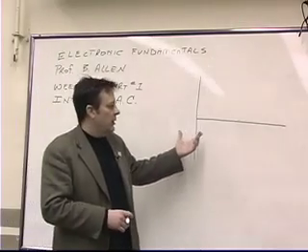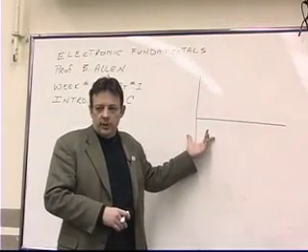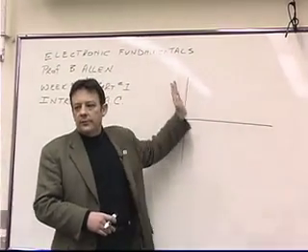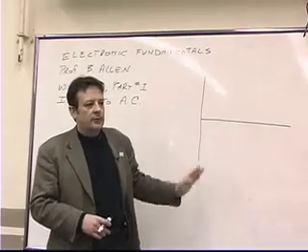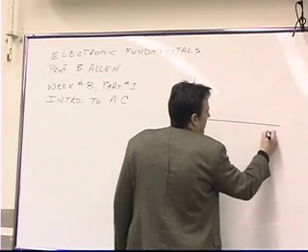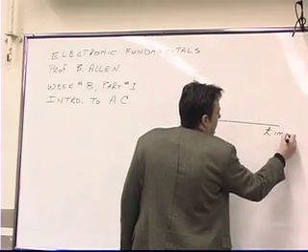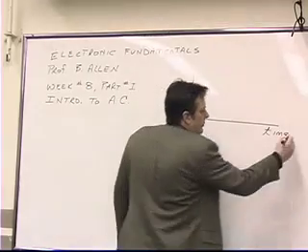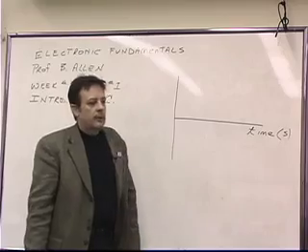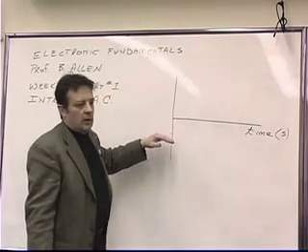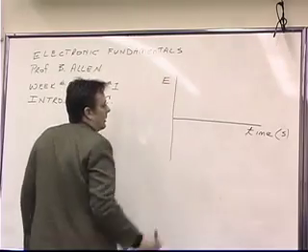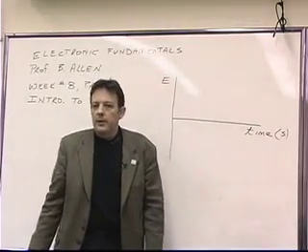This is effectively a Cartesian coordinate system. In other words, we've got a horizontal axis, we have a vertical axis, which is our x and our y axis. Our x-axis, our horizontal axis, is going to be labeled with the units of time, and we're going to have seconds as our base unit. The vertical axis on an oscilloscope displays voltage. So I'll just put E to represent voltage because we're real familiar with that.